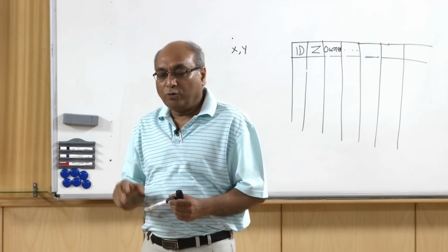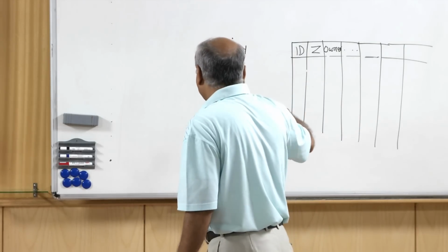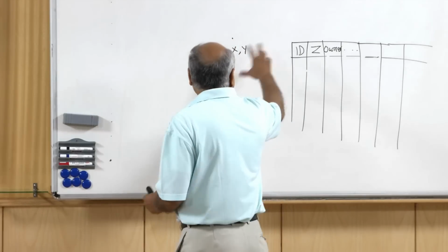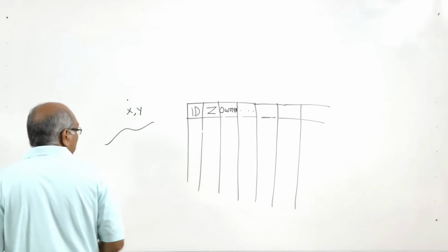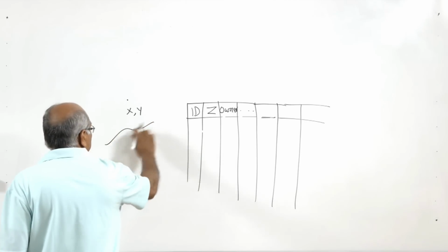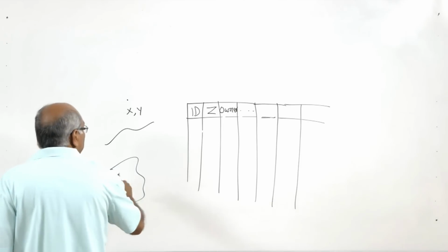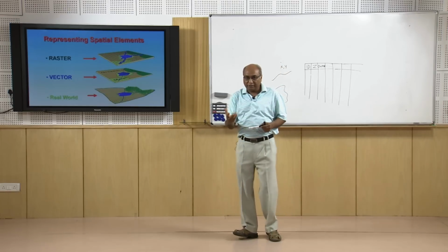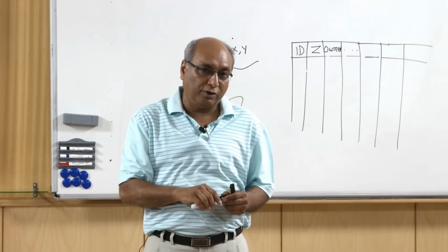So, one has to be a little careful while creating more fields against one single spatial object. Similarly, the same kind of table can also be there for a road or a stream, which is representing a line or polyline, and similarly for an area you can have an attribute table. So, the attribute table will always store non-spatial data which is directly related to the spatial objects.